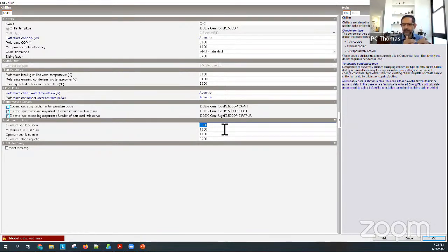And they are stable at that 20%. Okay, so then you have a way of saying, okay, when my low load chiller is running and it's running at 20%, okay, if I have 1,000 tons and this is only 200 tons, then it can run at 20% of 200 tons. That is the smallest capacity that I can meet. If my building needs less cooling, then I'm in trouble. Okay, if it's anywhere in between, no problem. The chillers can go up and down and work it out.